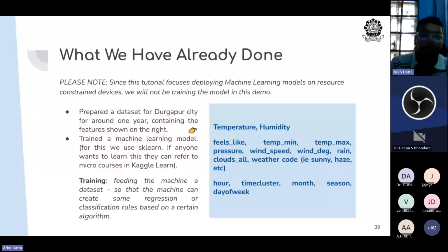So now we have two ways. One, using the dust particle sensor, we have got the ambient AQI from 1 to 6, and second, we have used the machine learning model on these features, and we have got data from 1 to 6. Now we can compare the data, and if the deviation is huge, then we can say that there is something faulty with my primary sensor, which is the dust particle sensor.